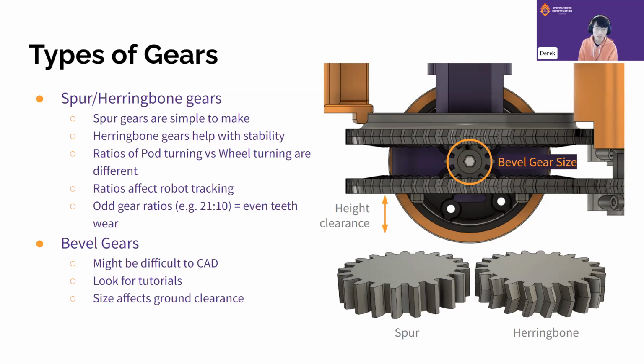And for bevel gears, they might be difficult to CAD, so it's always helpful to look for tutorials on how to make them. And keep in mind that the size of the middle bevel gear affects the amount of ground clearance you have from the bottom of the wheel to the bottom ring gear.